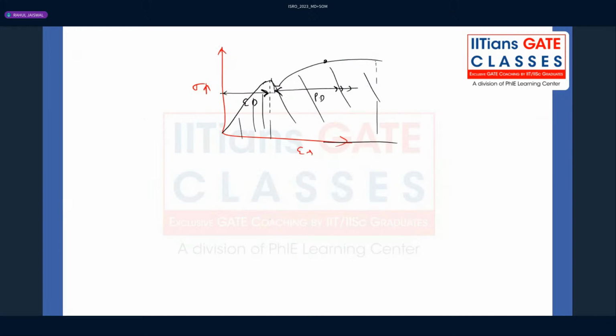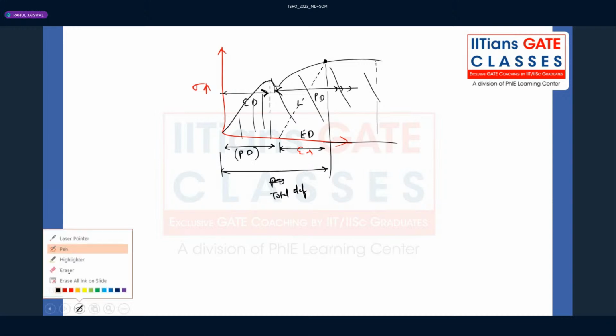If you load up to this point and remove the load, it follows this path, so a certain amount of plastic deformation is retained in the component.